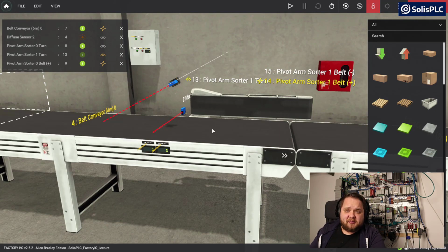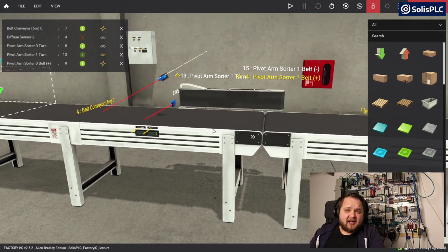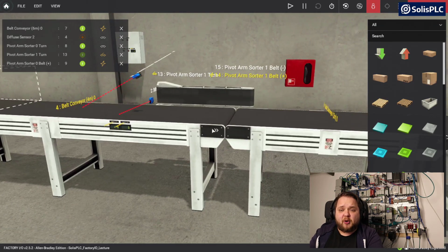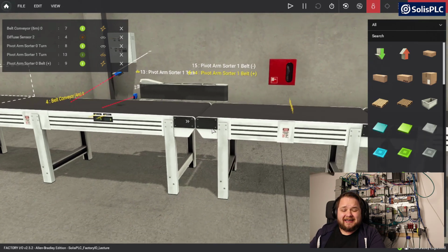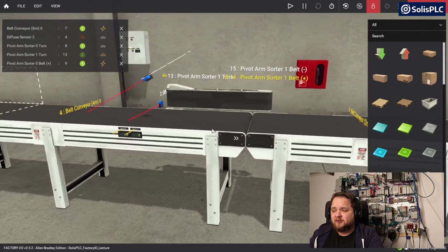A lot of times what happens is that you create a product. For example, this could be a registry on your case packer, and then your palletizer is in a different location in your plant. So you're going to merge a lot of those boxes on a single conveyor. You need to keep track of what type of boxes these are in an array, which is what we're going to be using to solve this problem. And then at the end of that conveyor, you will want to send them into different directions.